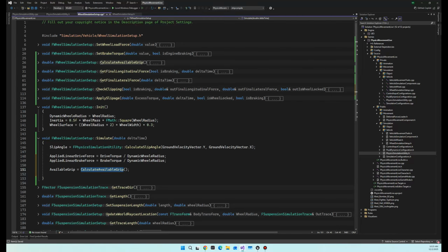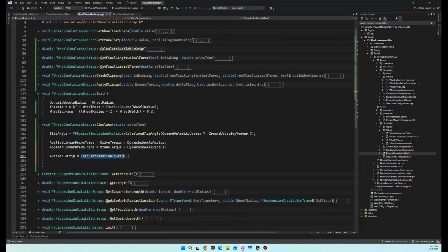If you're working with your materials team to create new materials, you can give a different friction value in there. We can pick that up and apply that to give vehicles a different feel. And this is happening per wheel. So if you've got one wheel on the road, one wheel on the dirt, these wheels are going to have different friction forces, which will create different forces on the vehicle as you're driving.